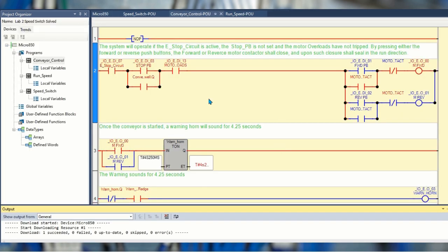Alright, so when we first started up, I've got the start button, the stop button was made. Notice I'm still running because it was running beforehand. So we'll let that stop. It's all finished. Okay, good. Let's reset our stop. Nothing is confirmed. I'm going to press it in the forward direction, so our forward push button. And it's going to take a bit of a scan for that to become true. Once it becomes true, I can let go, and I'm running forward.